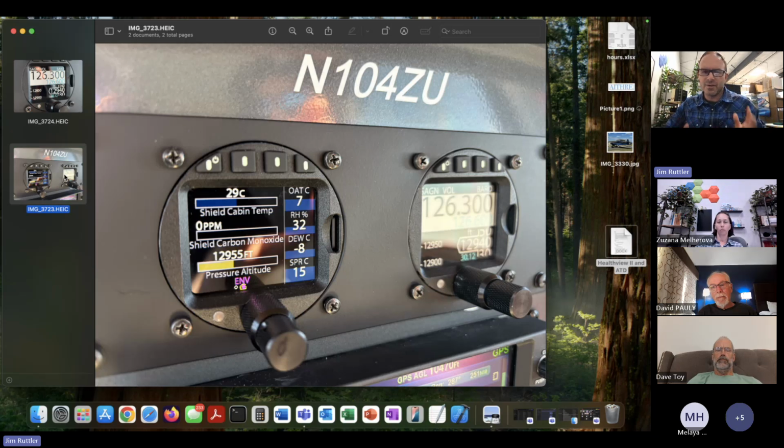I talked to Mark and said, Mark, are you sure this is going to work? He said, oh yeah, it's going to work. So I had no idea how to do this. It's the first time I really worked with radios. I took the Dynon radio out and hooked up the comm: transmit and receive, the speaker and the audio phones, and then power and ground, and there's a push to talk pin. And the radio worked with my current PS Engineering intercom.